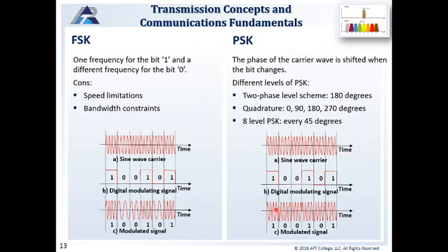So instead of this signal going up and continuing on its upward stroke, we've modulated it. We know it's a 0 because that signal is going down. In this example, we're using 2 phases, so they're 180 degrees out, but you also have quadrature and 8 level phase shift keying, where you would have every 90 degrees for quadrature or every 45 degrees for an 8-part signal.